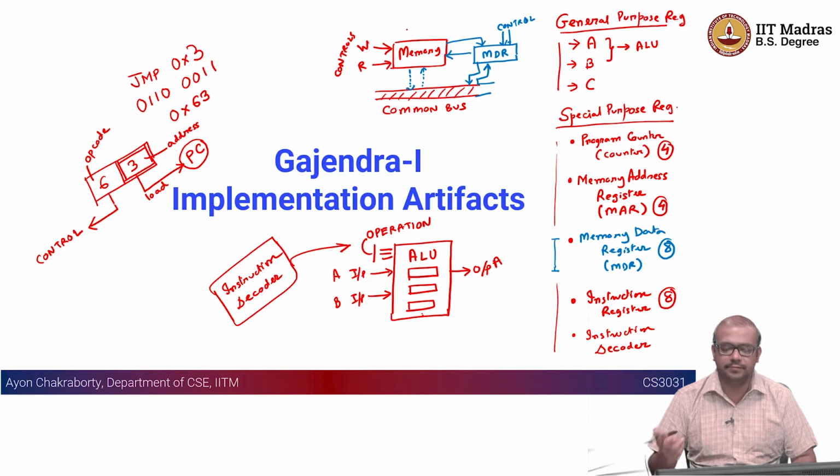For example, even if a multiplication instruction is not available in our ISA, if you provide an add instruction, and some mechanism to repeat things over a period of time, like a for loop, so a jump instruction in our case, or a jump with some condition like JNZ, JC, and so on, we should be able to realize multiplication functionality using those instructions.